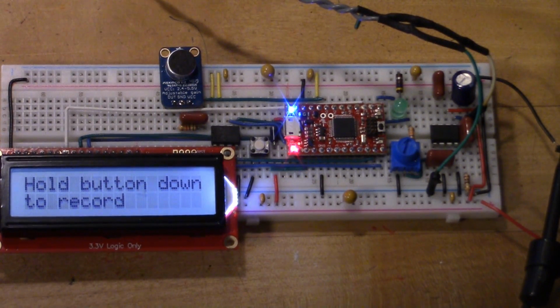There's a finite state machine that knows what state we're in, whether we're waiting to play a message or waiting to record a message. When we press down the button, it times how long the button is down. Once it's down a second, it goes into recording mode. If it's released before a second, it starts to play. If there's nothing to play, it goes to an error message. So there's just a few states in there.